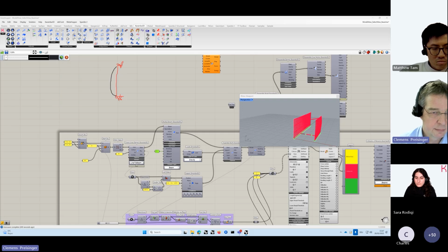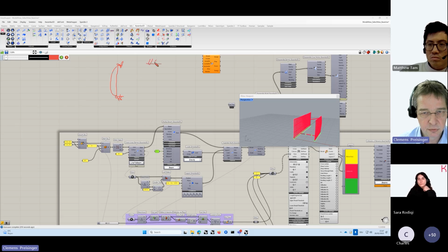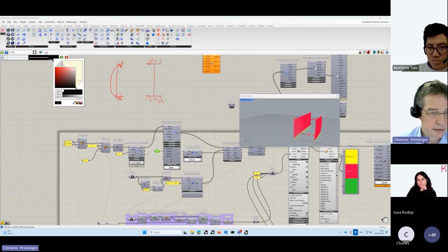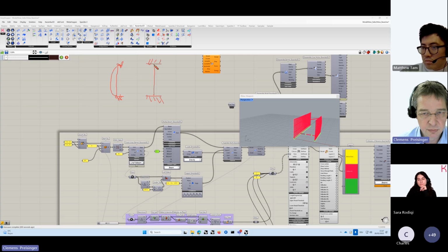If you have different boundary conditions, like for example a fixation so that there are no rotations possible, like at the floor slab, and here maybe also, then a column in between will buckle differently, namely in such a way that here there's no rotation possible, so it will go like this, and then like this, and this, and there will be inflection points where the moment is zero, very much like here.